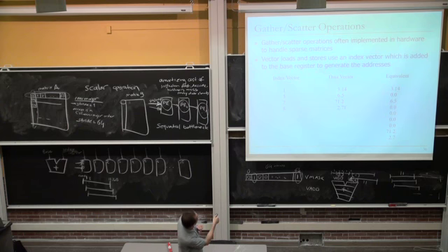You can think of this as the stores also. You have this index vector, and this is the data you generated in a vector register. Now you want to store this data in memory in a sparse matrix. You want to store the first element in location 1, the second element in location 3, the third element in location 7, and the fourth element in location 8. So you do an index store. That's called a scatter. Scatter is the store, gather is the load.